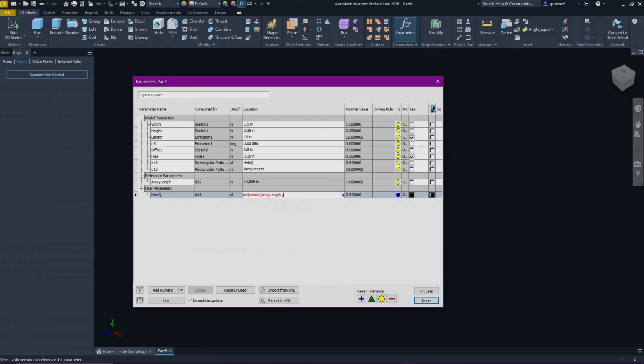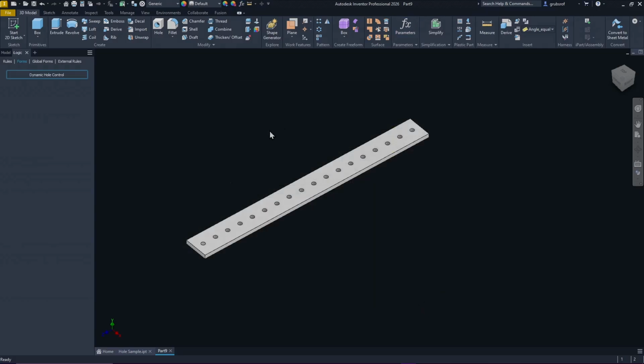Okay, space, we're going to add bracket. Now I want the spacing to be 2, so let's do 2 inches on that. And now, as we're adding a semicolon, a UL, semicolon, UL, you'll see it turn black, so that means the parameter is right. But you will still want to close it out. Say OK to that.